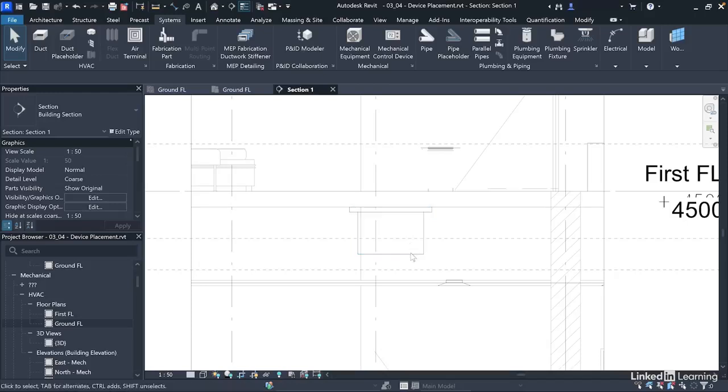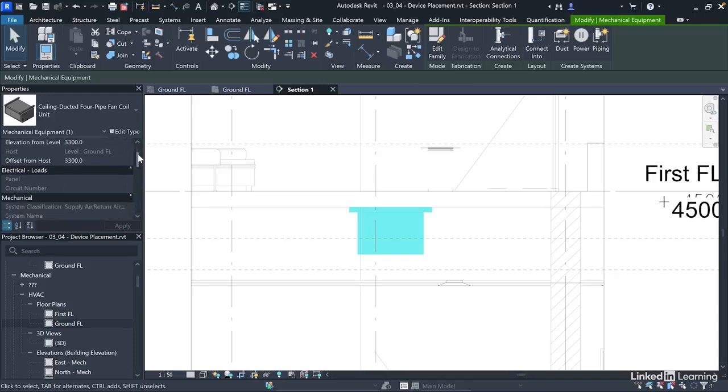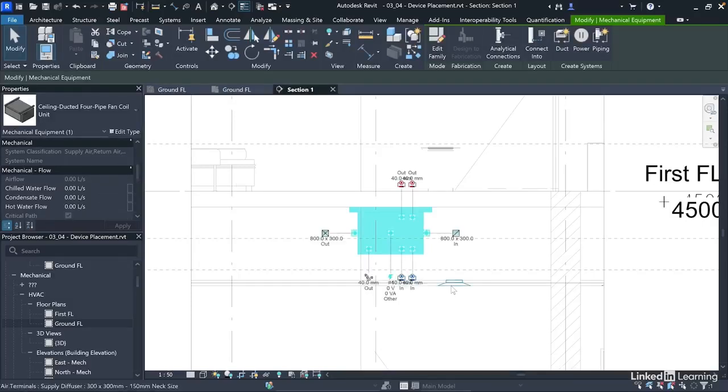Now if you select this mechanical equipment, unlike the air terminal that will specify the airflow, you will notice that the airflow is not editable. And that is because we've set this to calculated in the family. So for a parent component for this system, it actually has to calculate from the child components when we physically connect them. So that is why this is currently grayed out. The moment we connect the child components, which are the air terminals, it will calculate and populate this value.